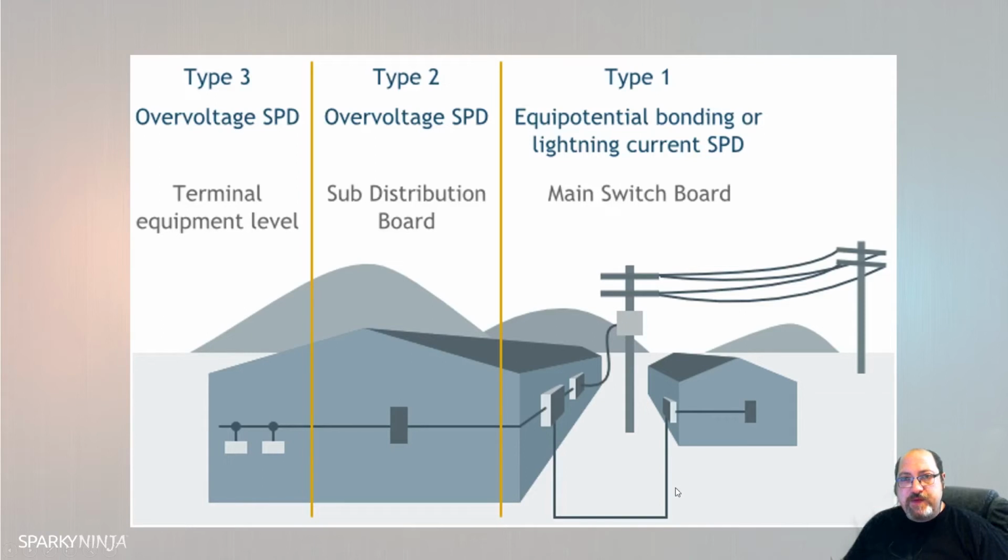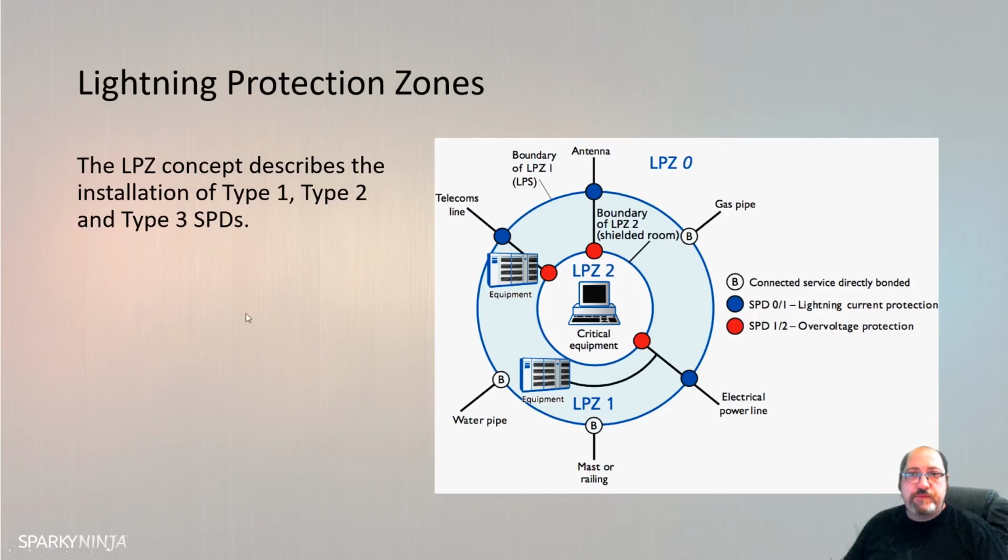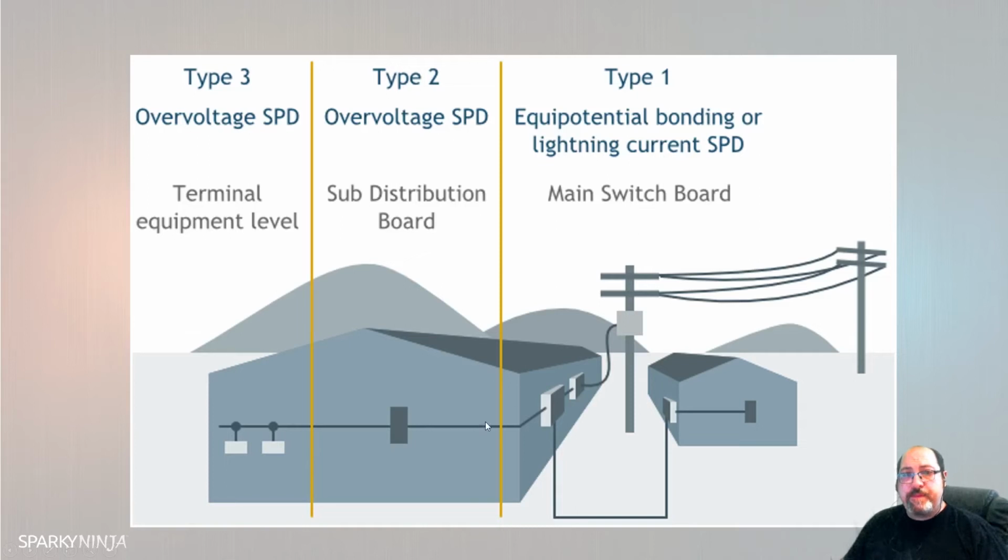And if there's any cables underground or anything that's underground like pipes or telecoms or power lines, antennas, they're potentially going to induce that voltage because they're going to be running underground, and then as this voltage goes along, it'll induce that voltage into that, and at the end of those is either a CPC being connected to a main earthing terminal to an earth reference, or there'll be a main protective bonding conductor to the pipework, again going to the main earthing terminal to a 0-volt reference.